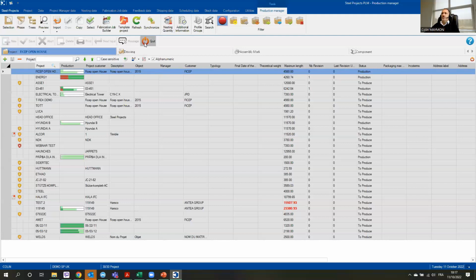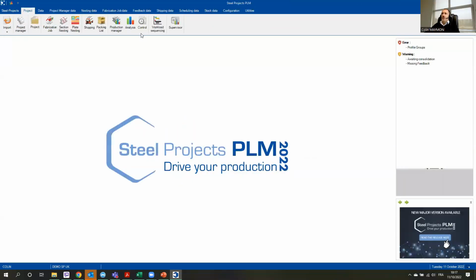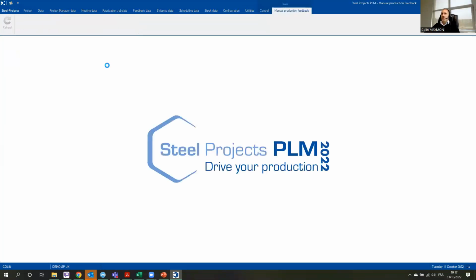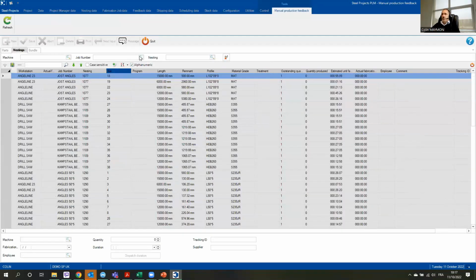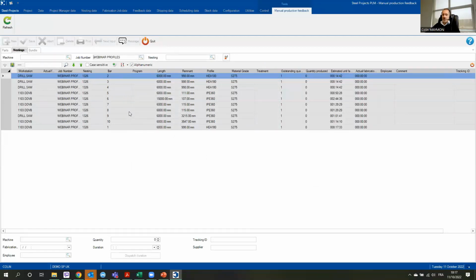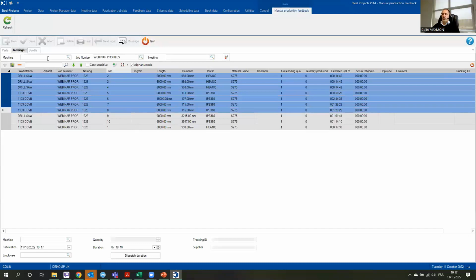You've also got the possibility to manually feed back. So if I go on Control here, on Fabrication Manual Input, I can select my nesting. Okay, here is the webinar profile, and I can see some items. I can declare that, okay, all that has been produced.